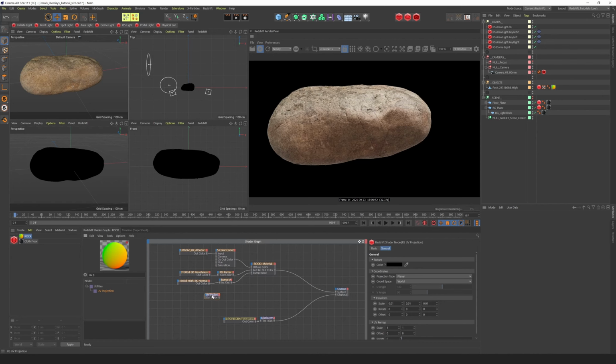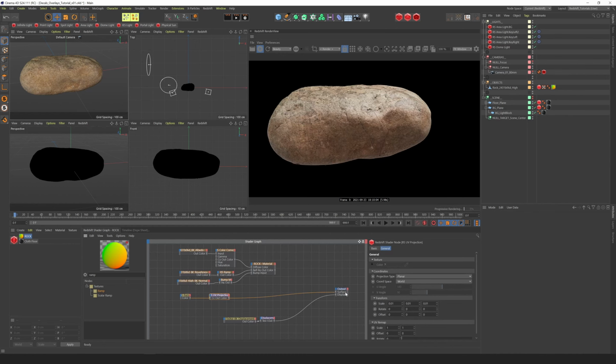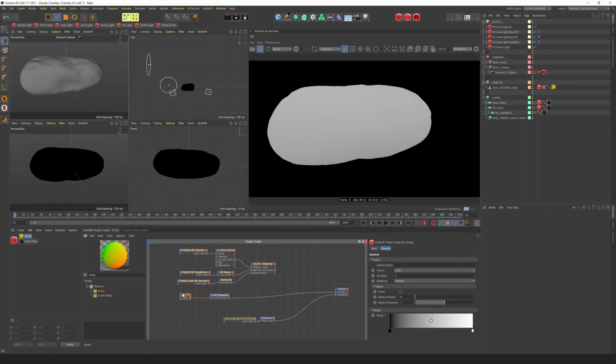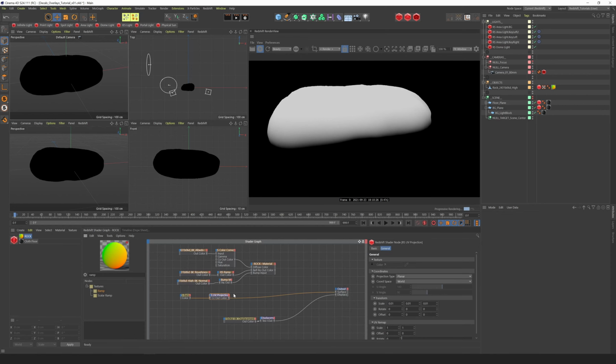And so if I drop that on to the shader graph along with a ramp, I can just plug the ramp right into the texture color input on the UV projection node and select that to go to the surface. So we would get something, but let's go back and check our ramp. The ramp is set to vertical, and we can sort of clamp this down, and we start to see that, just like you'd expect, the ramp is being applied top to bottom on our object. But the nice thing about the UV projection node is that we have more control over this on our object.